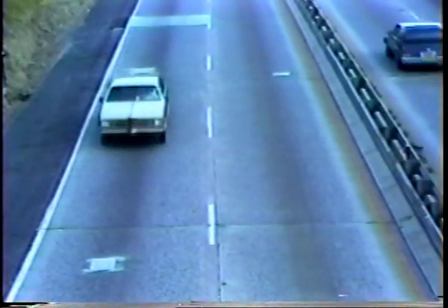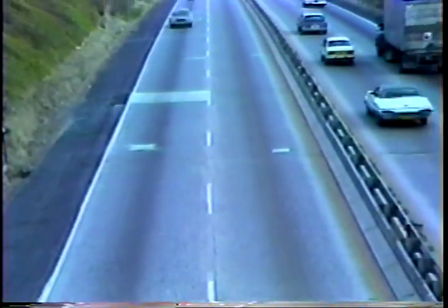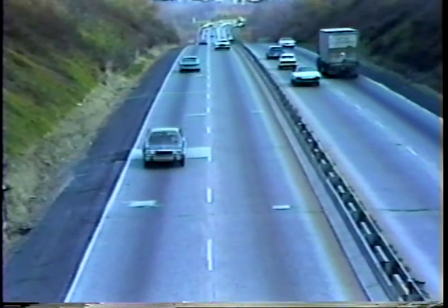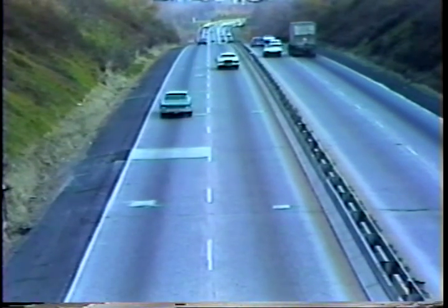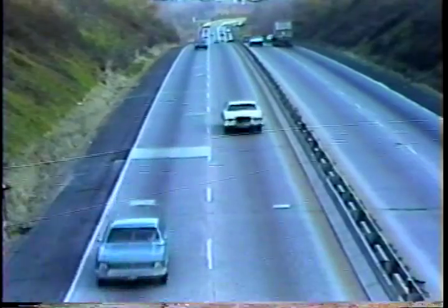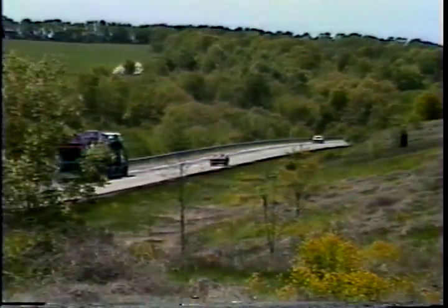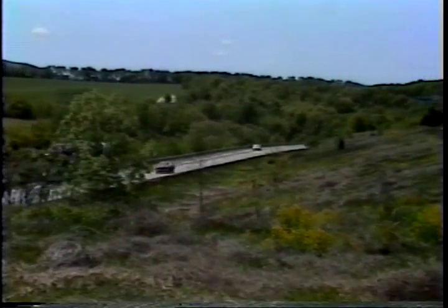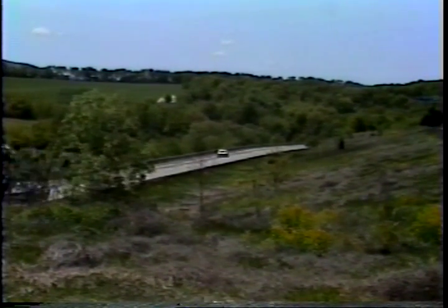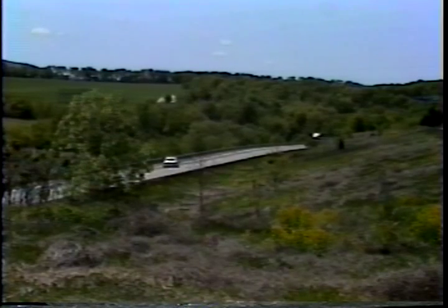The repaired pavement can be opened to traffic immediately after the concrete has gained sufficient strength and the joints have been resealed. When the appropriate construction practices are followed, partial depth repairs can be a very cost-effective way of repairing pavements for early opening to traffic.